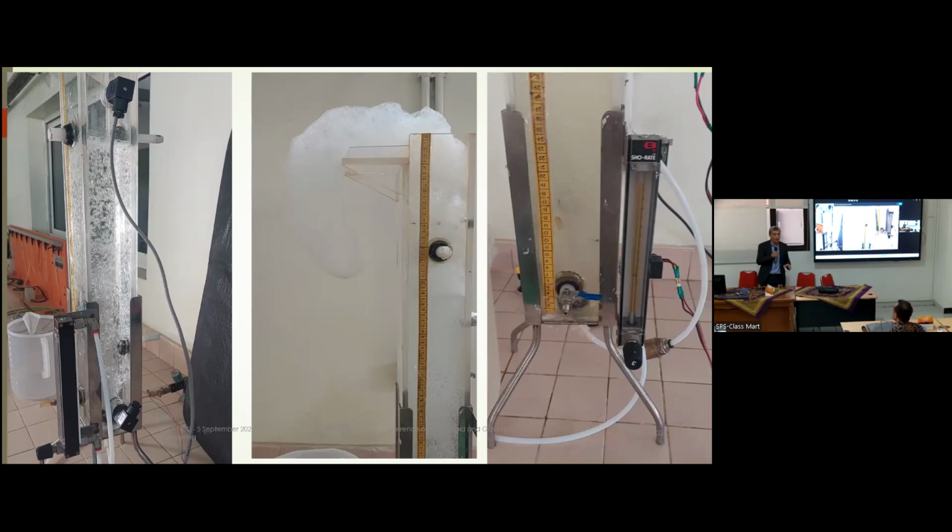What do you think about many bubbles or not many bubbles, according to the condition that we want? We prefer many bubbles. To maintain the bubbles, we have to master the size of the bubble. It's very important. What we call gas hold-up should be higher, because the quantity of gas should be in the solution, the liquid. Don't let it quit the liquid rapidly.